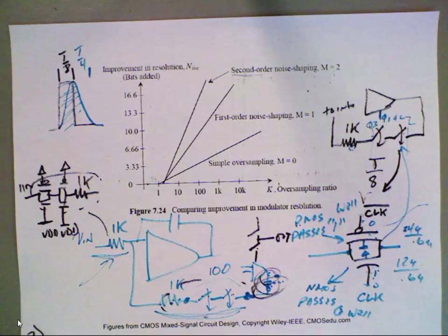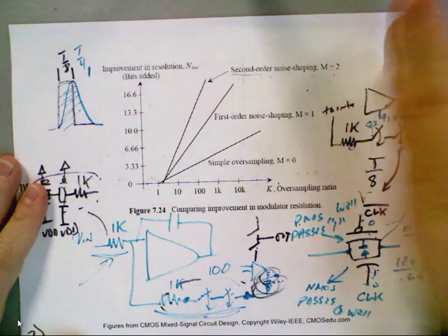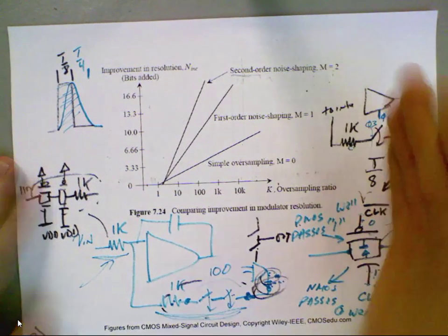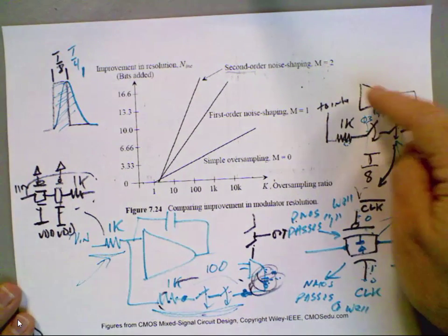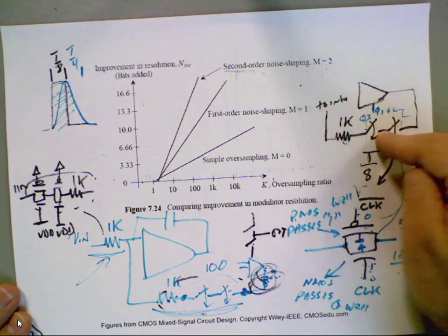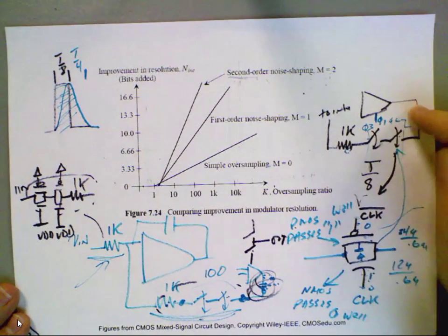If you put ideal stuff in, everything's good, because you can make the clocks like the example I put on the web. You clock this and then you immediately clock these. No delay. That's maximum SNR. Then you can slow down and the SNR is going to be the same, right? But if you have a real comparator, you can't do that because the comparator has some finite time to make a decision. So you have to clock these a little later so you make sure the output is fixed.